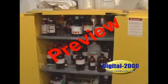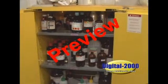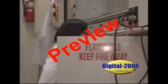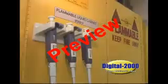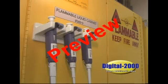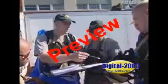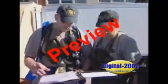Storage of dangerous chemicals should be limited to 1 day's supply, consistent with the safe and efficient operation of the process. The storage should comply with applicable laws and ordinances. An approved storehouse should be provided for the main supply of hazardous materials. Local fire departments should be notified so they'll know what is stored where and can plan for emergencies.